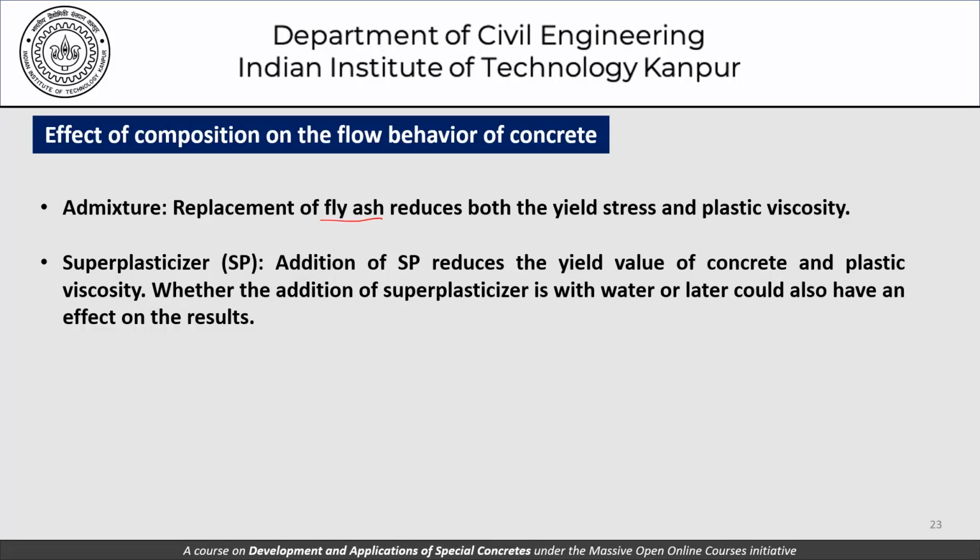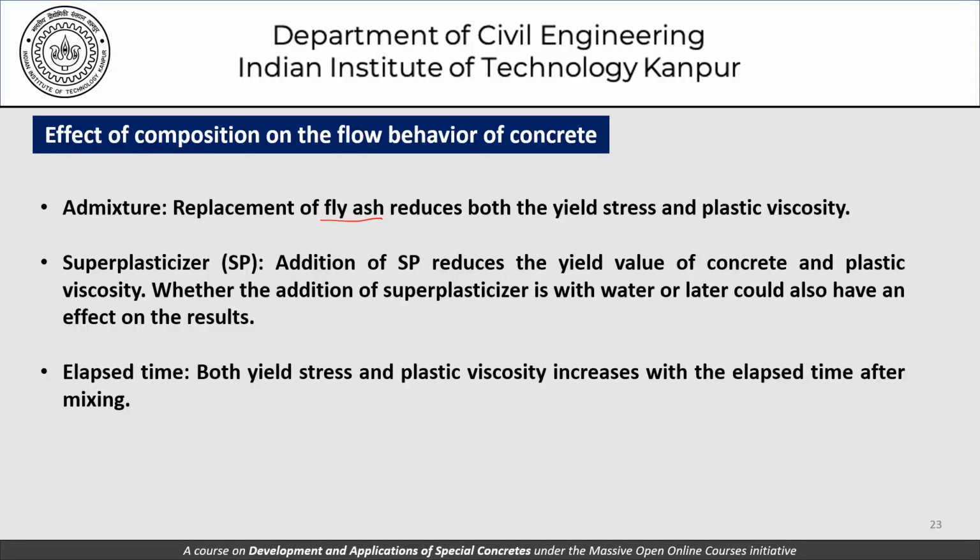Elapsed time: both yield stress and plastic viscosity increase with elapsed time after mixing. This is a direct reflection of the hydration that will happen. Hydration does not necessarily mean that it will suddenly become hard. The concrete is still hardening, and that hardening process in rheological terms is reflected by an increase in the yield stress and plastic viscosity values.